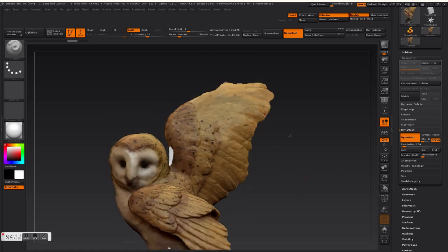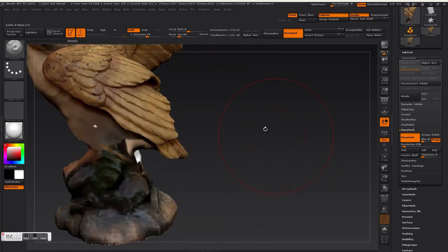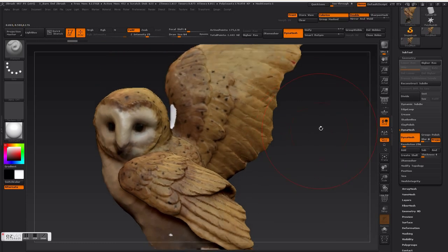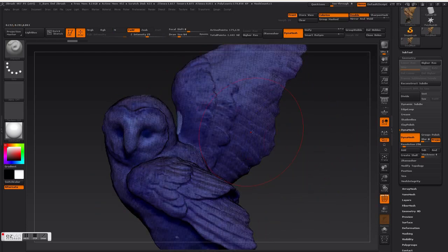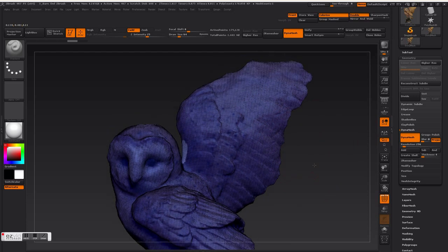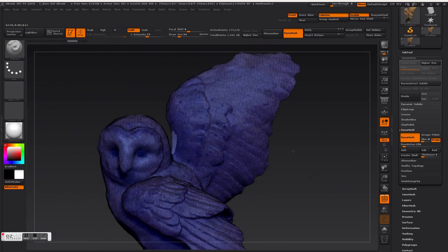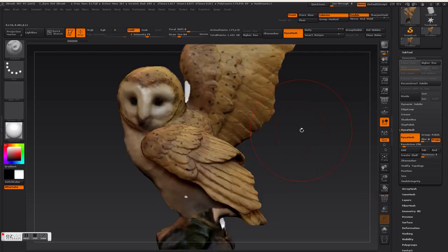Okay, so we've got our mesh here in ZBrush, and to get it into Mudbox, we're going to need to have some UV maps. Now we did have some UV maps before, but because it's been dynameshed, it's lost those UV maps. With UV maps, you need quite a low polygon mesh to actually create one in ZBrush, and this is quite high. It's on 178,000 polygons.